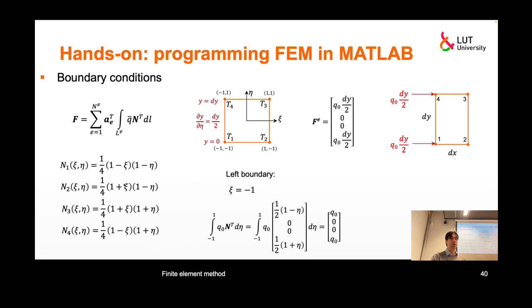And those two shape functions, number 2 and number 3, are immediately eliminated by this multiplier 1 plus xi. So on the left boundary, I always have N2 and N3 values 0 for any element actually. Okay, then I also substitute this -2 here. Then it gives me 2, and 2 by 4 gives me 1/2. And so I calculate this integral for left boundary in local coordinates.